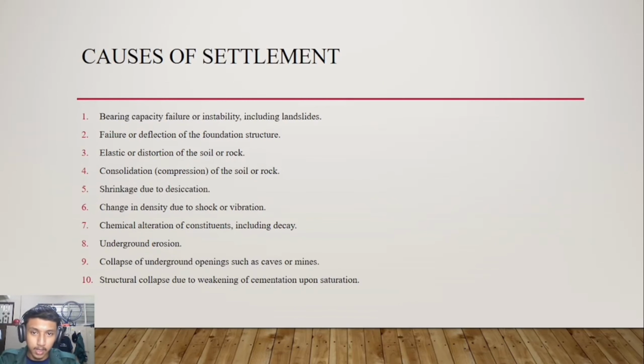The causes of settlement. The first one is bearing capacity failure or instability, including landslide. Second, failure or deflection of the foundation structure. Third is elastic distortion of the soil or rock. Fourth, consolidation, compression of the soil or rock. Fifth, shrinkage due to desiccation.